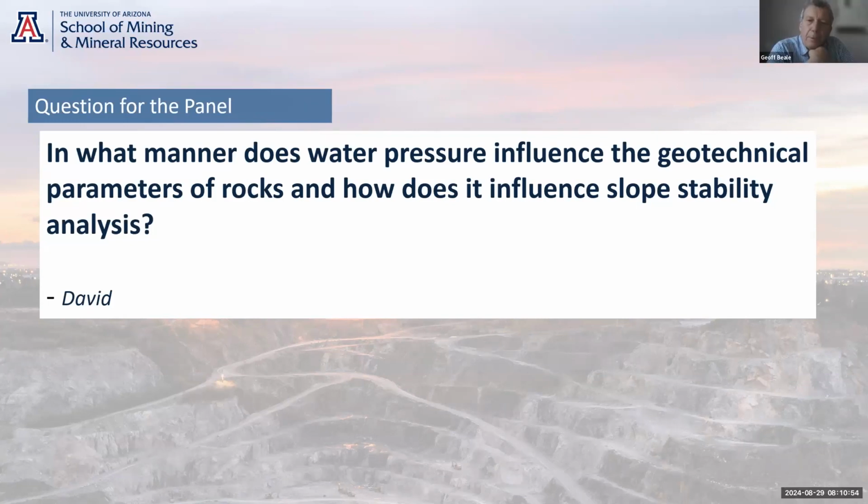Okay, so the main influence is on the term effective stress. If you can think about a plane or two surfaces, or you rub your hands together, or two plates of glass together, they're held together, and any geotechnical surface is held together by the weight of material above that surface. So the weight of the material holds that surface together.